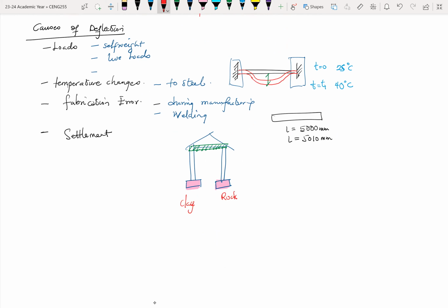All right, especially if it's wet. So let's say you put this building up in the dry season. So in the dry season, the clay is hard, behaving as though it's rock. So they both are on the same level. All right. Then comes the rain. All right, the wet season comes, where the water table in the soil goes up.